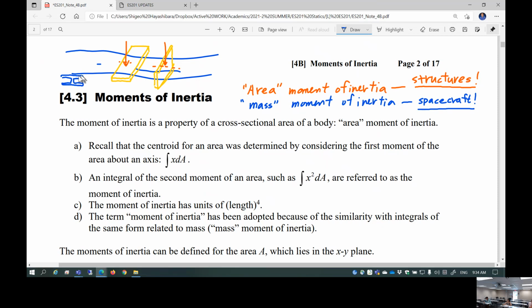This is the cross section, and then I'm going to make a bridge out of this. This is probably the optimum solution. So if this is a 1, this is 9 times stronger, this is probably 30 times stronger, resistive against the bending moment, which is the loading you are going to take for this structure. What is the difference? The only difference is the cross section.